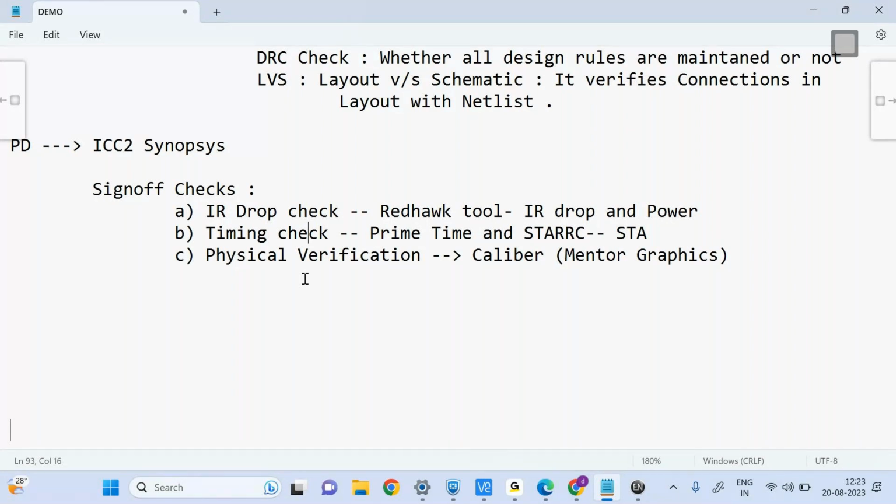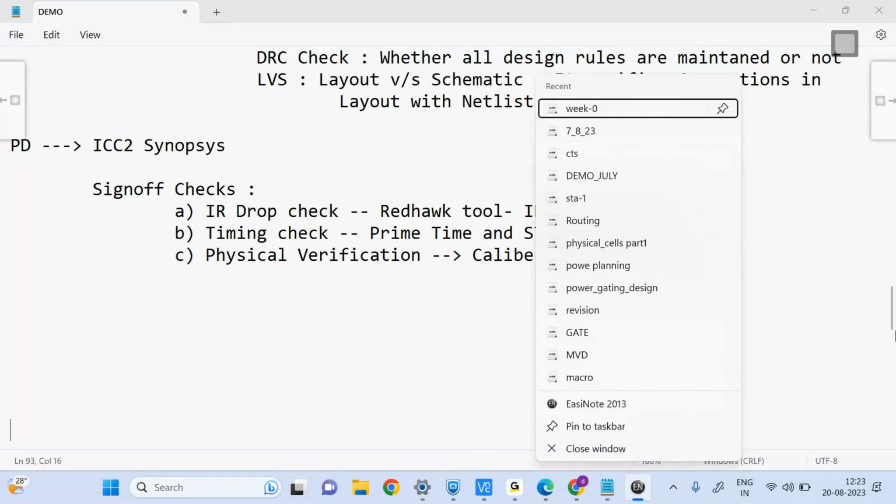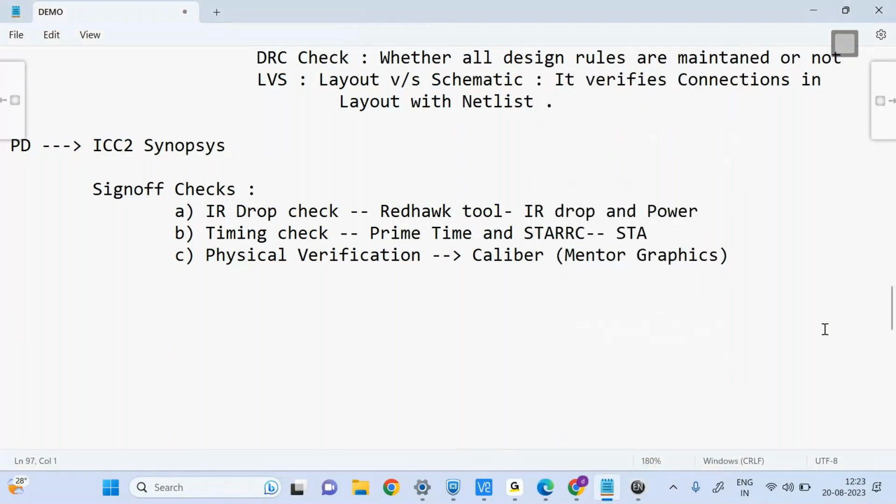Full chip level designer will take what? This full chip level designer will integrate all the blocks. He will take the GDS2 file. That GDS2 file is forwarded to the foundry. This is the flow that the IC designers will follow.